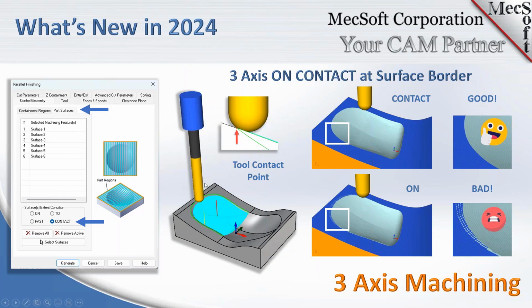So in 24, we added a new condition called contact. Whenever the tip, for example, if you're using a ball mill, whenever the machining ball of the tool makes contact with that perimeter edge of the surface, it stops.